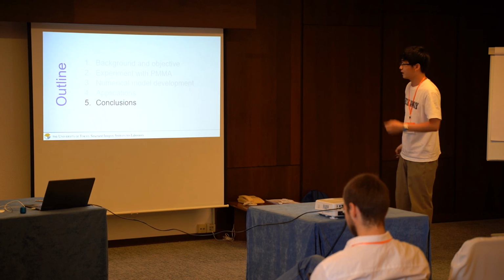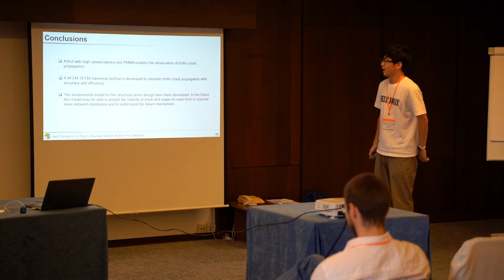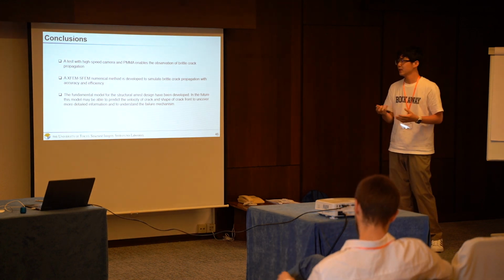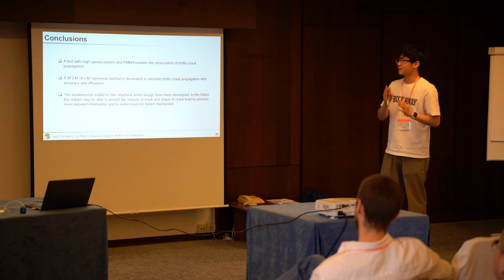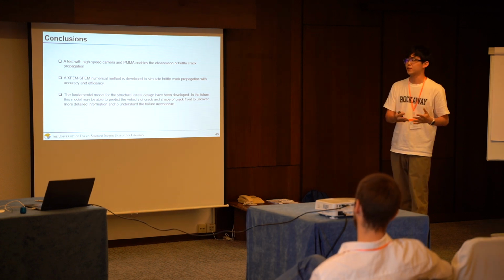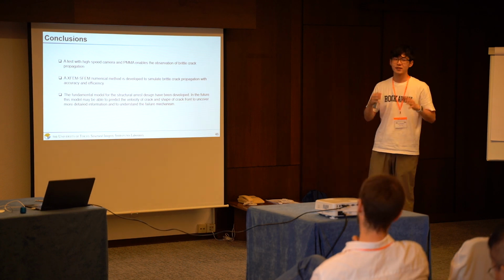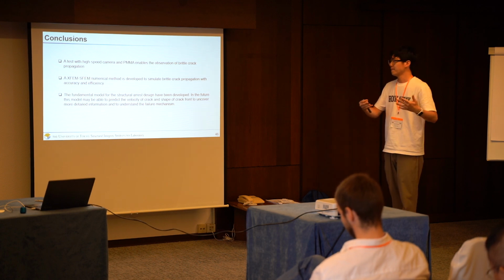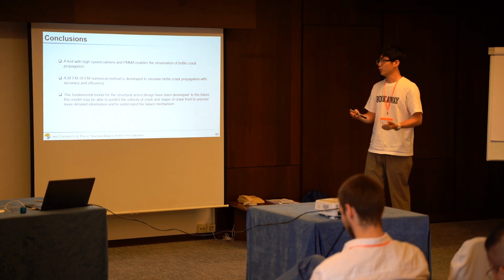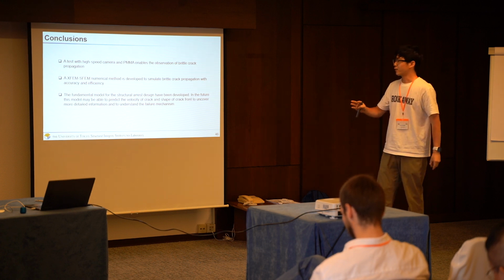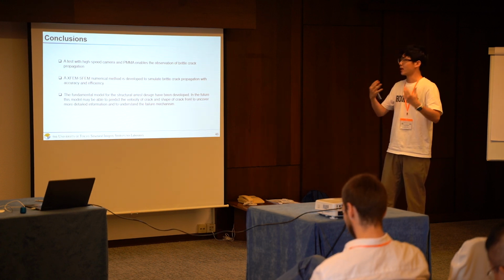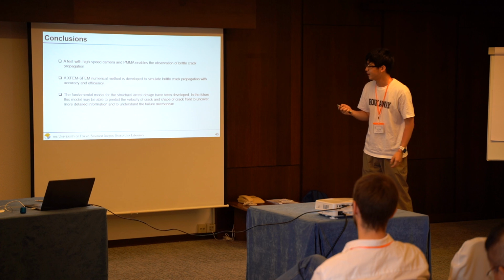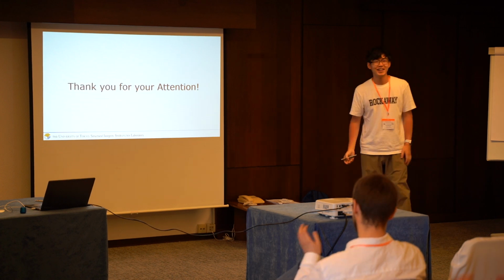Finally, let's make a conclusion. A test with high-speed camera and PMMA enables the observation of the brittle crack propagation, and the XFEM plus SFEM numerical method is developed to simulate brittle crack propagation with accuracy and efficiency. The fundamental model for the structural arrest design has already been developed. In the future, this model may be able to predict the velocity of the crack or the shape of the crack front to uncover more detailed information about the fracture mechanism. Thank you so much for your attention.